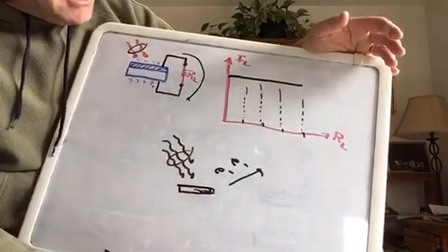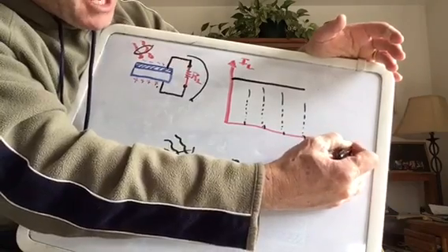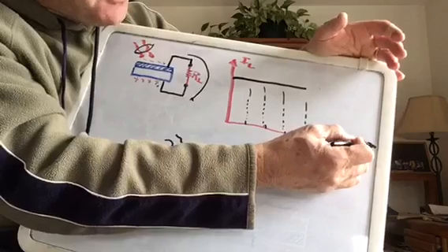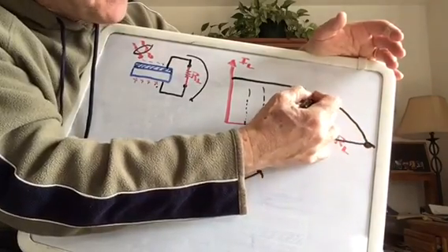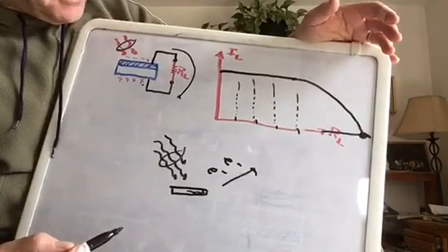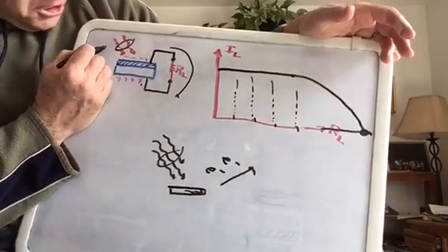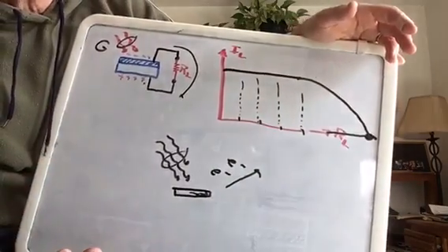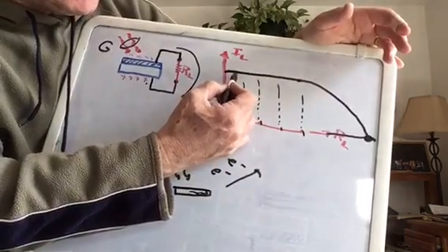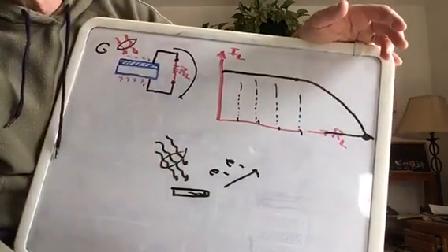It is true that if we hook up a really, really large resistance, somewhere way out here like this, we're going to get 0 amps. And so in theory, we might get something like that. Okay, now that's not exactly right, but the main point I want you to think about is, hey, let's think about a PV generator at a certain solar G: 200 watts per meter squared, 400 watts per meter squared, 1,000 watts per meter squared. At that G, it's going to generate a certain amount of current flow regardless of the resistance that's hooked up.